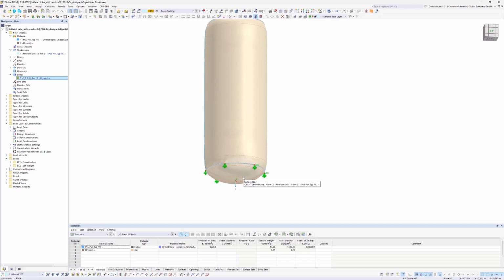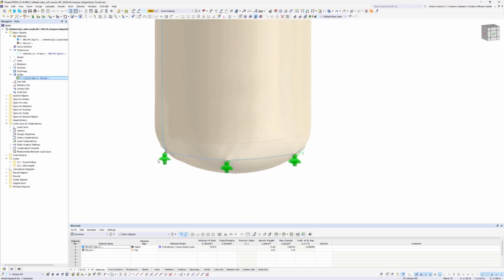or calculation convergence issues, because it's quite hard. So normally you would try to assign some nonlinear surface support to this, but this inflicts the whole calculation by a lot. So that's why I chose a different approach. I chose some nodal supports here. One of them is fixed, and the others are fixed in the Z direction, but not in the other planes.